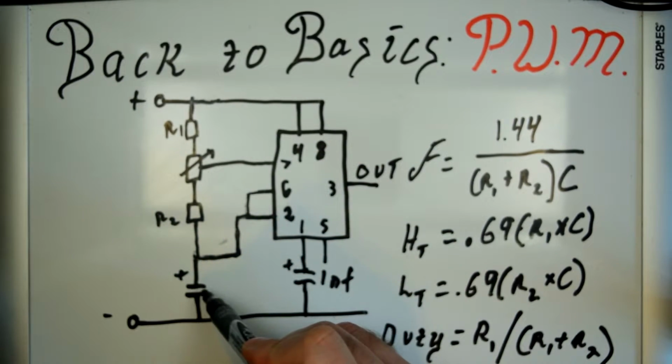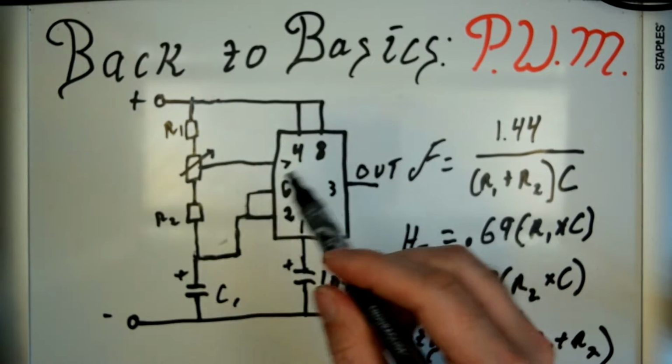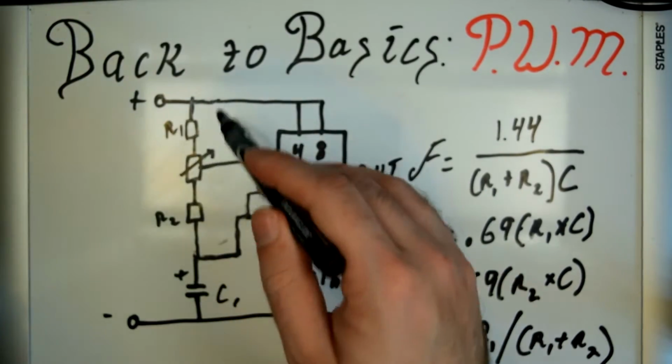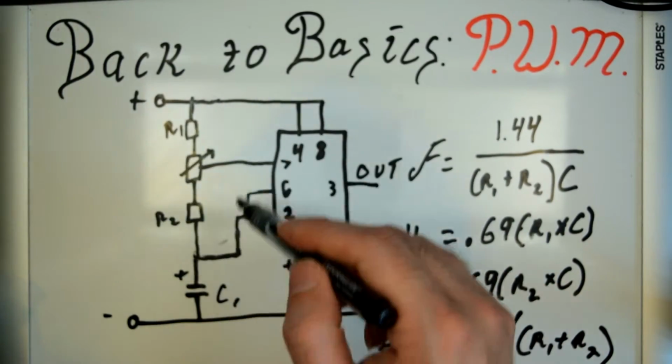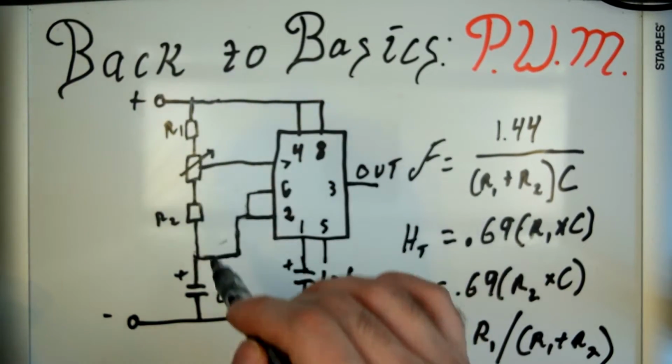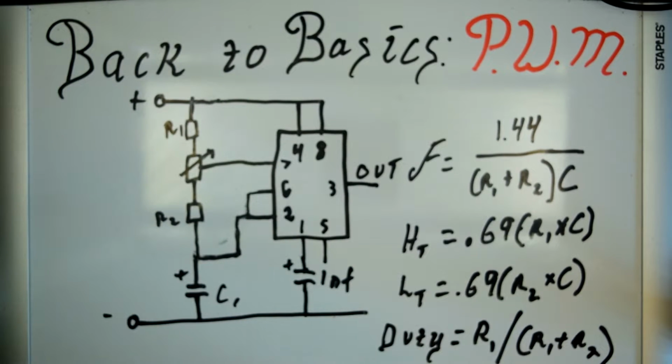and I changed the value of C to accommodate the frequencies that I wanted to see. So that's the easiest way to do it. Just pick arbitrary values for the resistors and then calculate C. So this is all of this on paper.